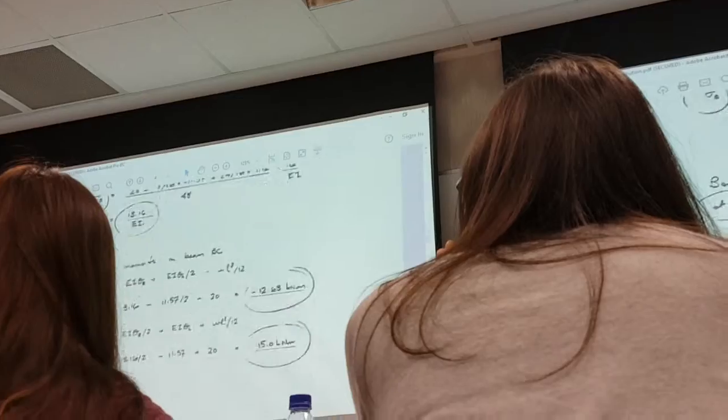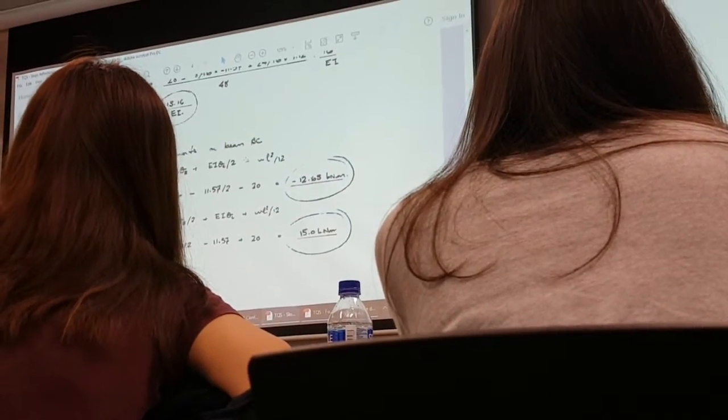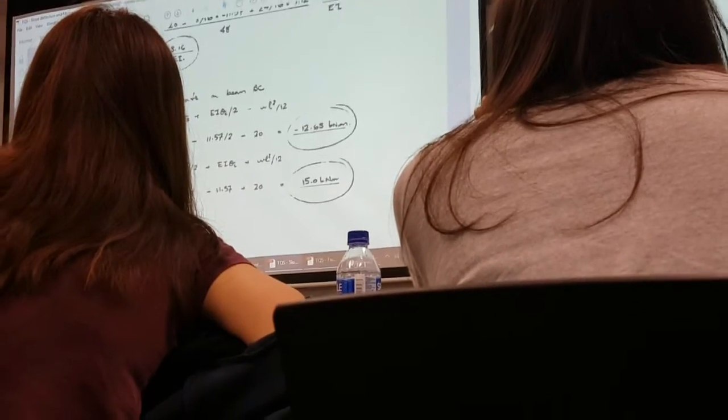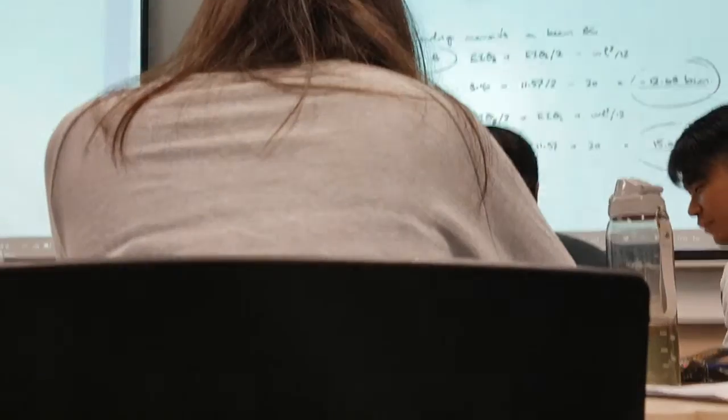But remember, for this case, is it just that straightforward? For member B, is it just EI theta B plus EI theta C divided by 2? No, right? You still have to add the fixed end moment induced in member BC. Remember in our example, page 8, we have gone through that already. If let's say there's a fixed end moment induced in that member, you have to add on to whatever fixed end moment over here. And for this case, why is it minus 20?